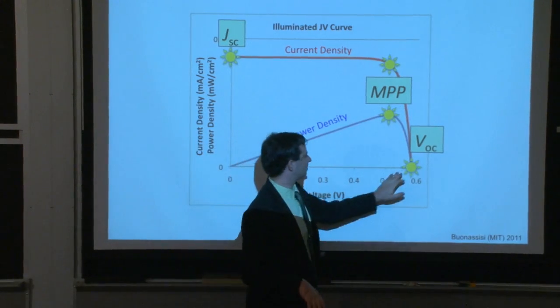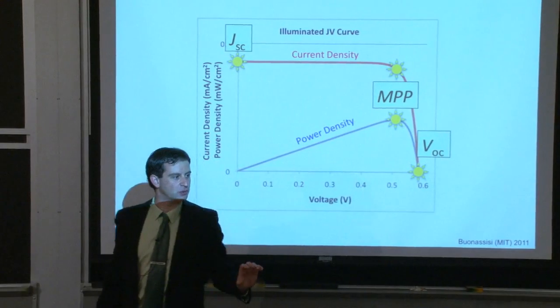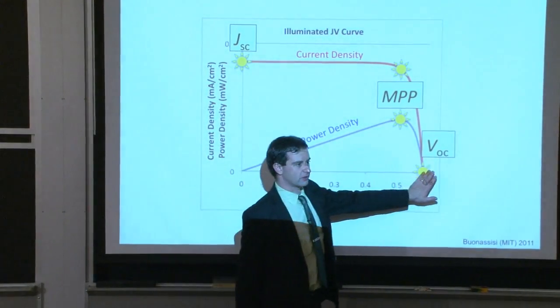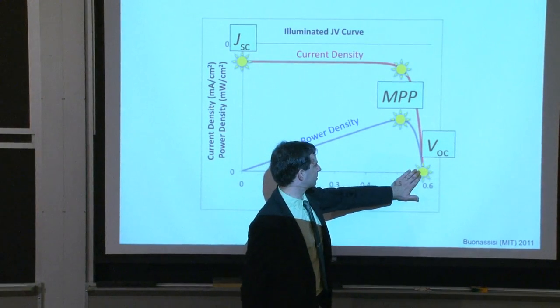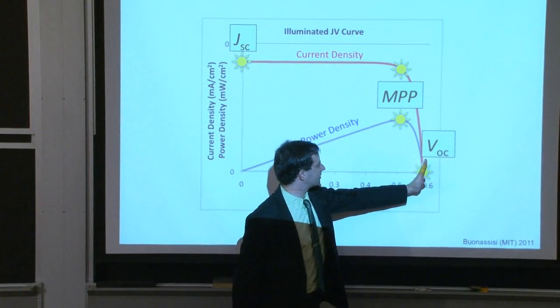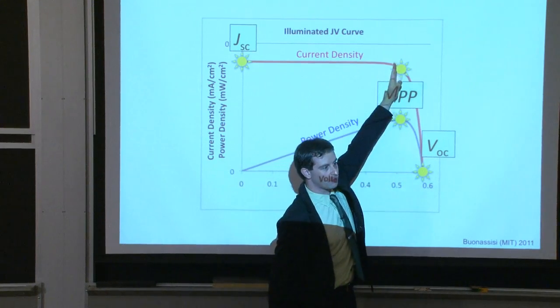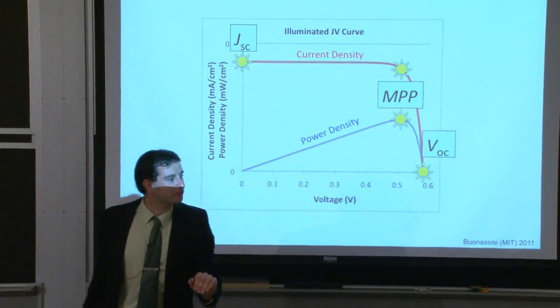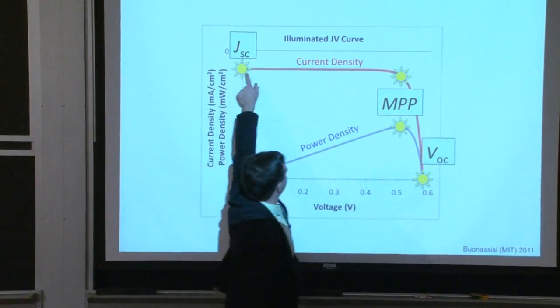I can show you a very nice little paper that describes why that is. It essentially has to do in part with losses inside of the solar cell, thermodynamic limits of conversion inside of the solar cell device. Then we've done another additional discounting from the VOC to the maximum power point, which we've assumed is around 0.1, maybe 0.2 volts. Notice the shape of the IV curve right here.